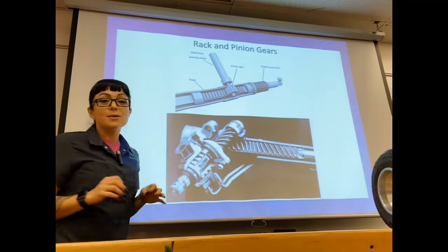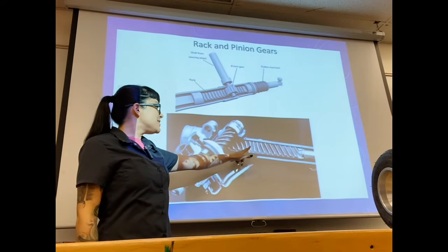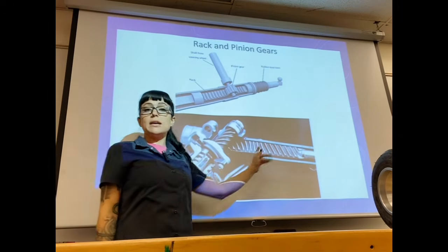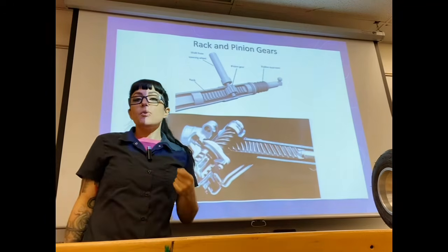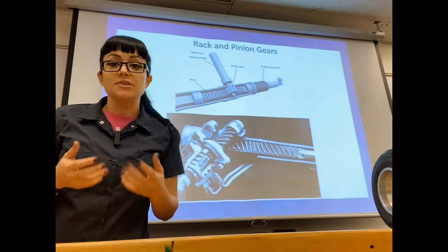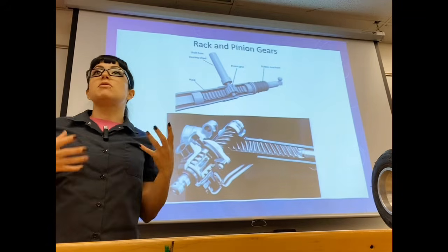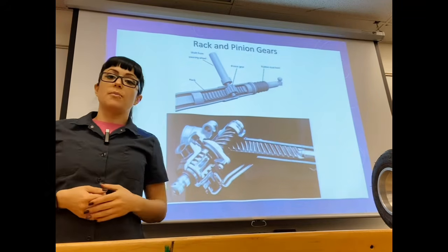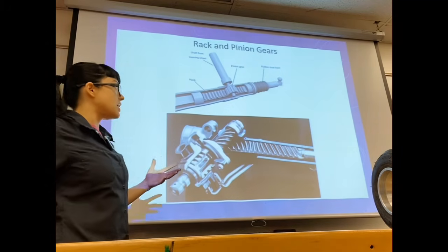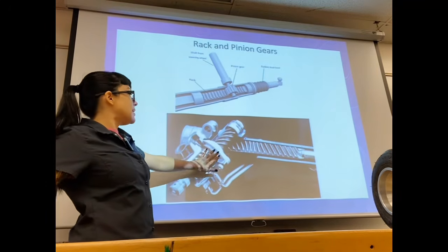Now, one thing I'd like to point out to you is that these gear teeth actually change angle as they go along. They get a little bit steeper and steeper. We call that a variable gear or a variable steering. The variable rack here allows you to get the best of both worlds when it comes to performance as well as drivability when you're driving around town and parking and things like that. Now, this is going to be part of our power steering, so I don't want to get into that quite yet.